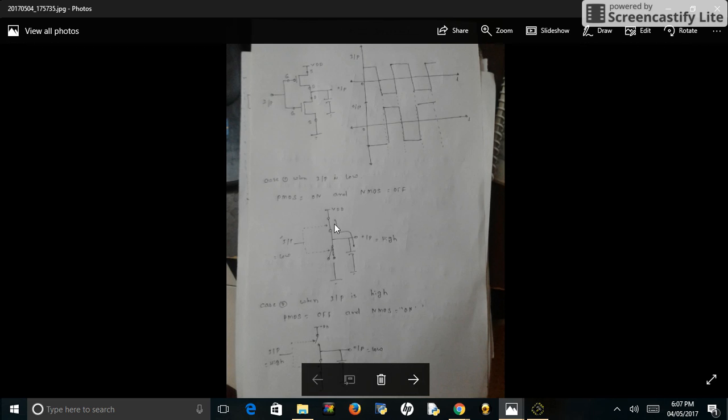So this is the equivalent circuit diagram of the CMOS when we apply input signal low. See, PMOS is on, so we replace PMOS by the short circuit, and NMOS is off, so replace NMOS by the open circuit. So see, output is directly connected to the VDD and capacitor. This is called parasitic capacitance present at the output terminal, which is charged through the VDD. So when the input is low, then output is high. Means it acts as an inverter.